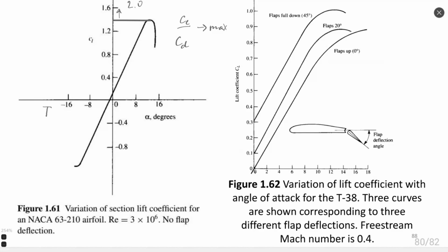You need to have a momentum coefficient within some limits. If you have too big or too low a momentum coefficient, you will need to compensate it because it starts to rotate all your structure in one direction or the other. You need to have, for example, a big tail that compensates the momentum coefficient.